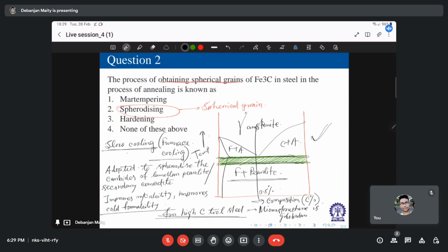Correct. And you can think of any kind of alloy tool steels, including those of the carbide class, as well as ball bearing steel, which also should have some globular structure in suitable condition for the best machining results.